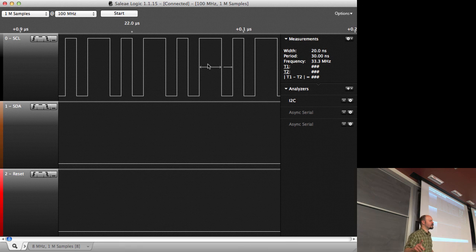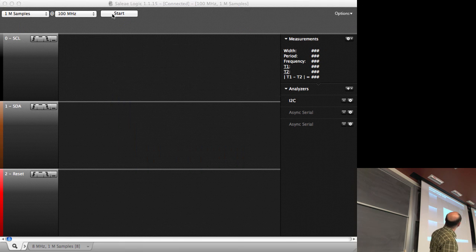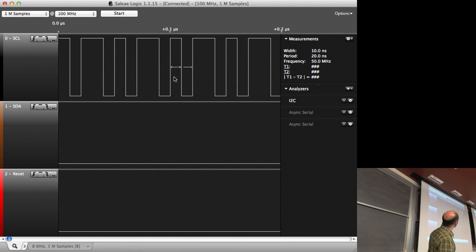In addition to that, we are also having a square wave. If you look at the frequency content on a square wave, it has very, very high frequencies involved. Right? What we would have to do is actually have a sine wave. So I can switch it over to a sine wave. I have not tried this out yet, so let's see what happens. Oh, it's the same thing. But on average, this will probably give you a 40 megahertz signal if you would average it out.